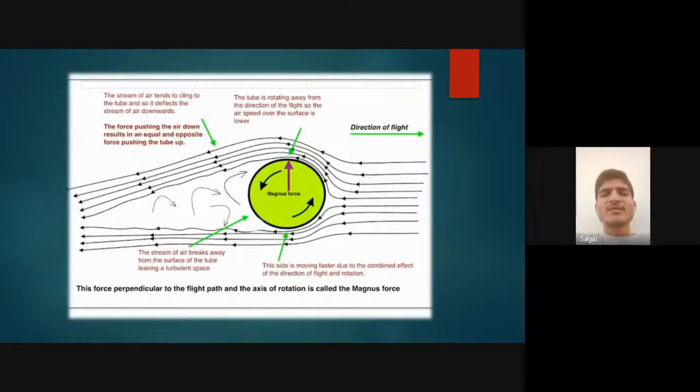If the flow energy is high, the capacity of the fluid to overcome the pressure gradient is higher compared to the lower one. If the fluid is able to overcome the pressure gradient, it remains attached to the ball surface for a longer time. But at the bottom it has less energy, so it will detach earlier compared to the top.